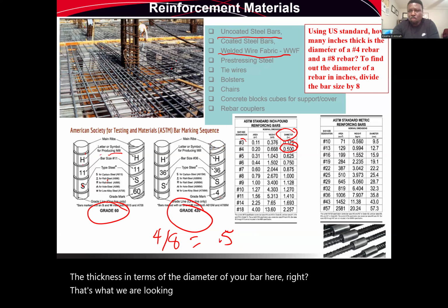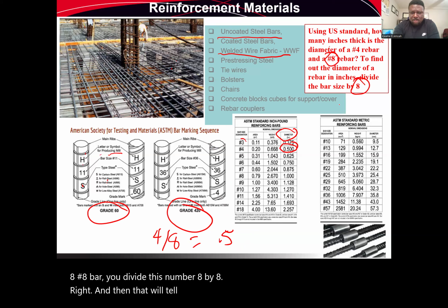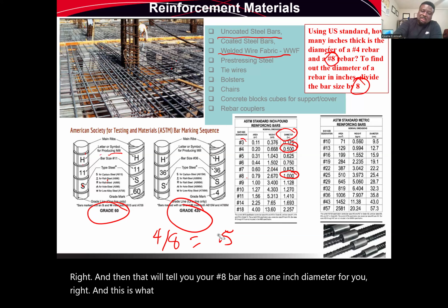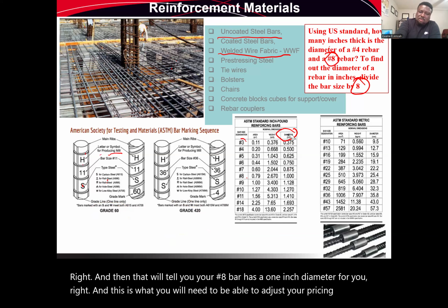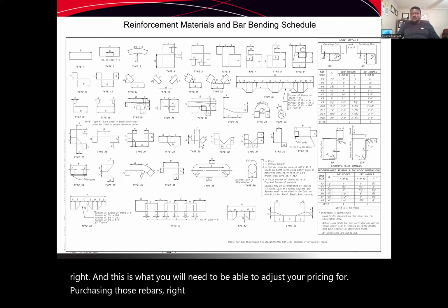The same thing when you pick the number 8 bar: you divide 8 by 8, and that tells you your number 8 bar has a 1-inch diameter. And this is what you will need to adjust your pricing for purchasing those rebars, right? I hope that makes sense.